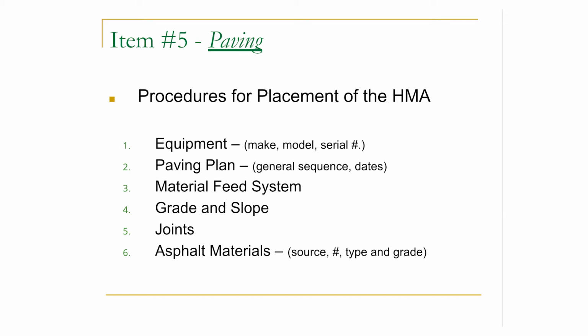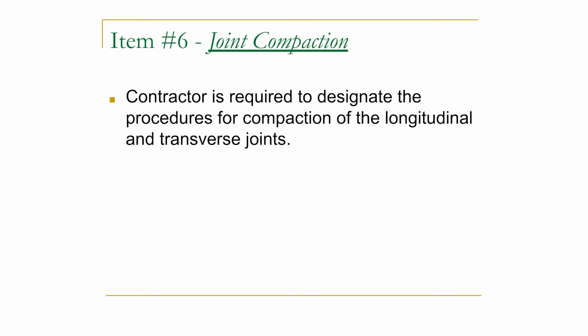Talk about your longitudinal and your transverse joints. How are you going to take off from a cold joint in the morning? You're going to set up on a piece of lath, basically, to allow for compaction. How are you going to overlap your joints when you're paving and compacting them? Transverse joints, are you going to cross roll them? You can spell that out in there. If you have the room, you can try to cross roll it.